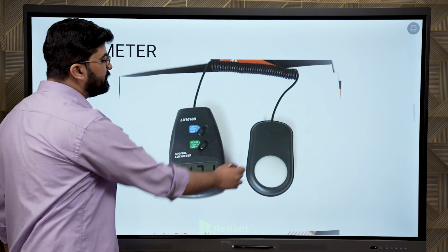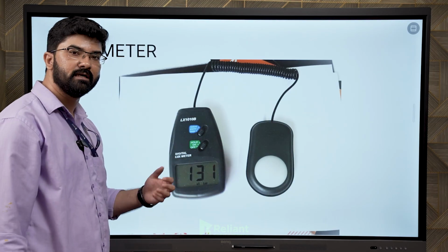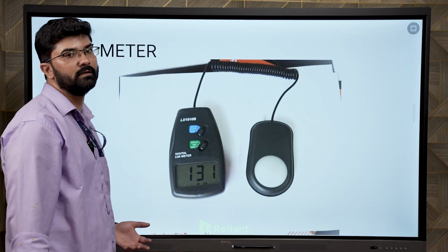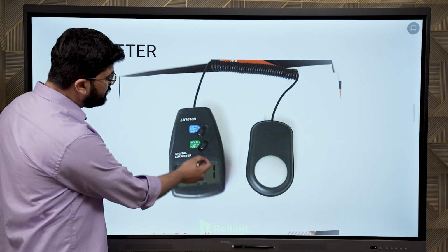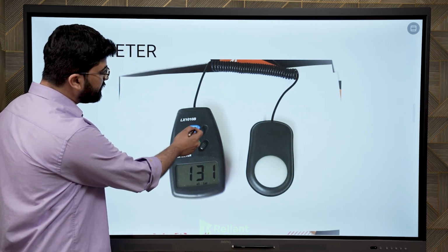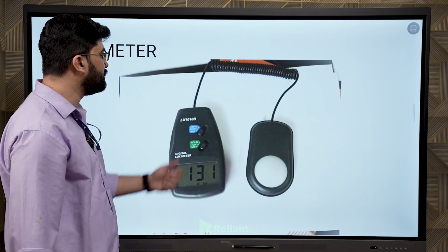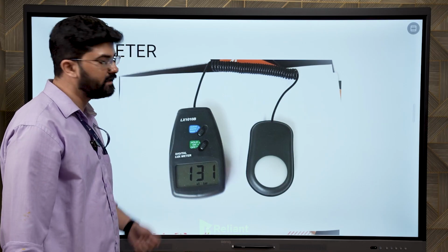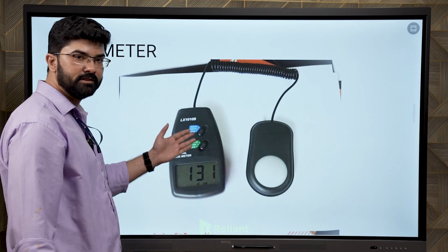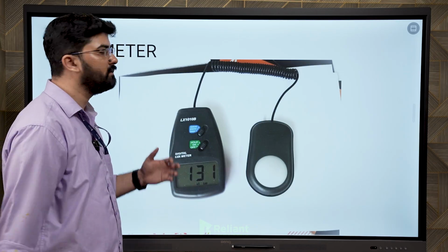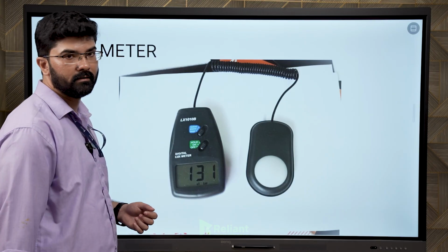So we have to open the sensor and check where the inspection is conducted. On the specimen we have to keep the sensor and check how much lighting is falling on the test object. Some amount of lux will be there, and here it shows 2000 lux, 20,000 lux, up to 50,000 lux. So the minimum is 300 to 500 in open space; in the plant or in the lab we need more than 1000, or at least more than 600 is required, as the minimum requirement.